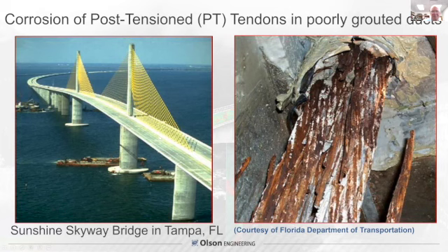This is a cable-stayed bridge. And they were actually, though, in these large piers, which were constructed because of the risk of ship impact to have some protection, but they had trouble grouting them because they had U-shaped ducts that went all the way down into the pier foundation, pier caps, if you will, and then curled back up. Well, they had real grouting problems, which led to a lot of void because of the saltwater environment of the Gulf of Mexico.